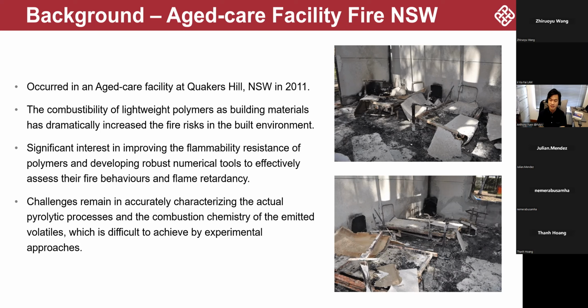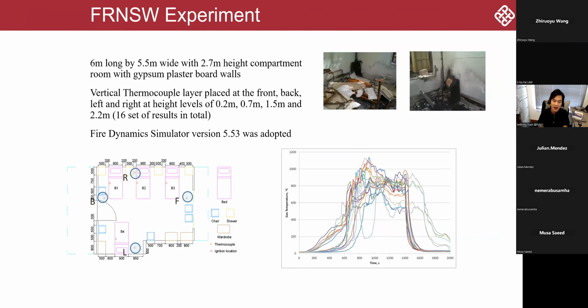And in this case study, we are looking into many burning materials, involving mainly polyurethane. But I guess the most important thing is to get the fire scene correctly. We struggled a bit in getting the actual fire scene. But eventually we found that the window breakage might be the most important factor for this case scenario itself.